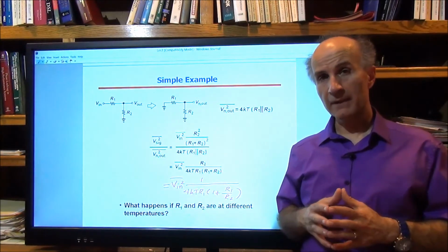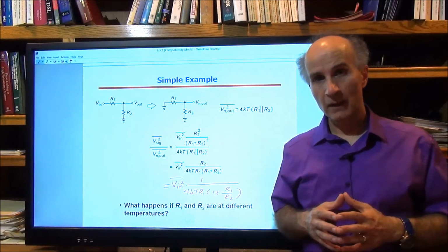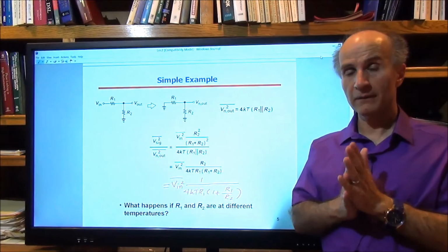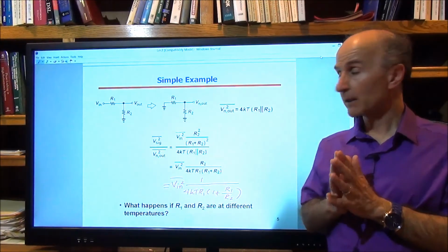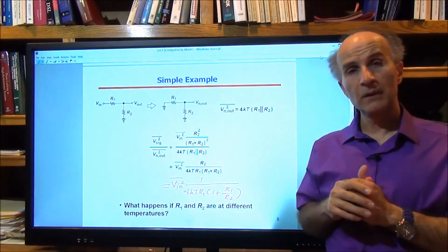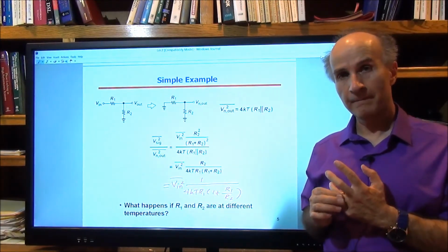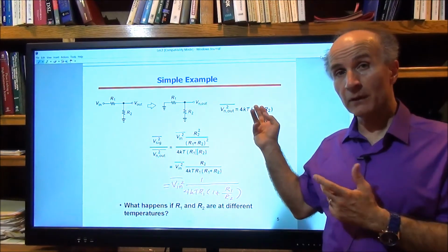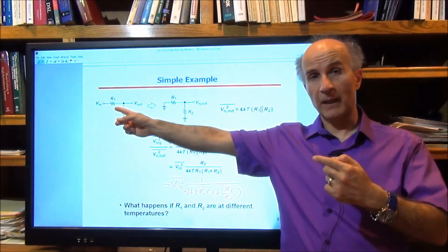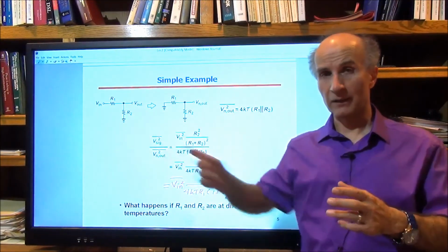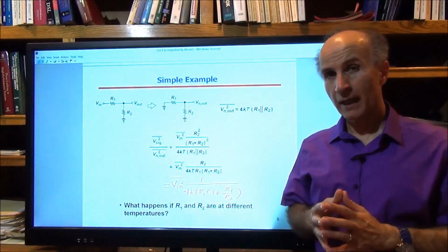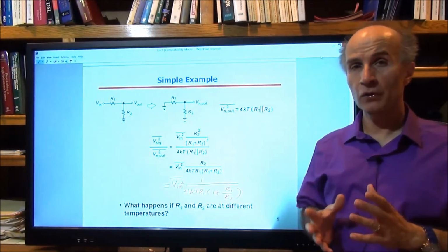All right. Now, but there's something peculiar going on here. Suppose I'm thinking of designing a low noise resistor divider, and this equation says that, well, you can reduce R1 or R2 to reduce the output noise. This equation is symmetric with respect to R1 and R2, but the circuit is not. R1 is in series with the signal path, R2 is in parallel.